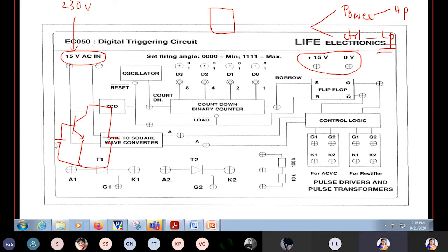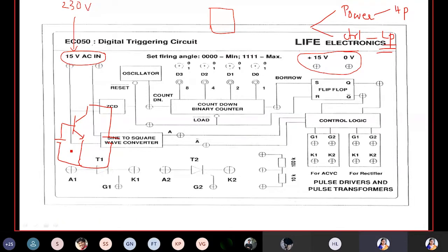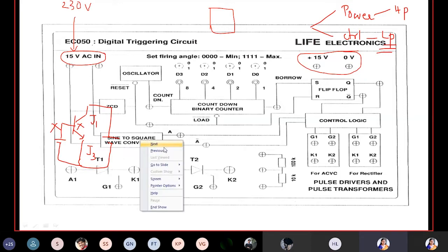Initially, when you are not providing this voltage, when this supply is absent, junctions J1 and J3 will be forward biased. J2 will be reverse biased, so there won't be any current flow through the device. Once you give the gate supply, the current flow through this will excite the electrons present in junction J2 and they'll cross junction J2 and move to junction J3.